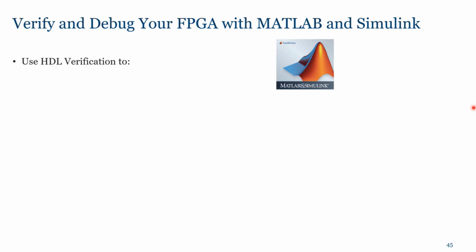Okay, so just a small note to say that even if you do only MATLAB algorithm development, and later on you prefer to still write your HDL code, just know that the test benches that you used during the validation of your algorithm could be used later on for your HDL code, right? So you can import your HDL code and use the same workflows that I'm showing here.